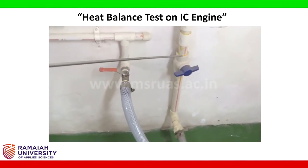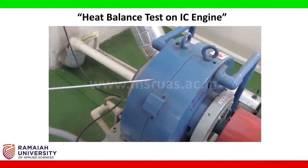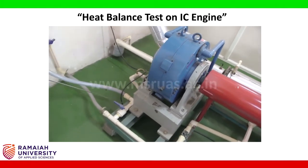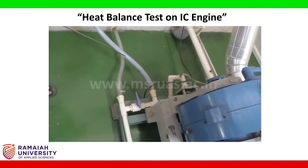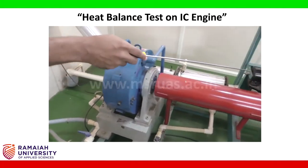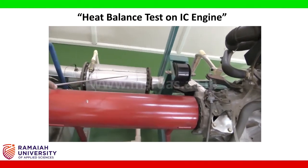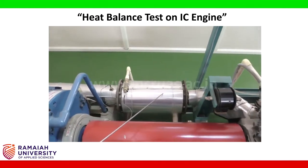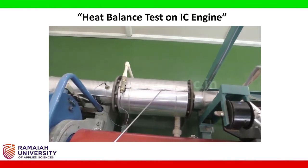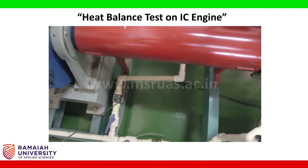Also the eddy current dynamometer is here. This is also a water cooled eddy current dynamometer. This is also connected to the water supply line here. And whatever exhaust gases are coming out of the engine, this is passed to the exhaust gas calorimeter here. For this also we have to supply water, so for that purpose there is a water line here.